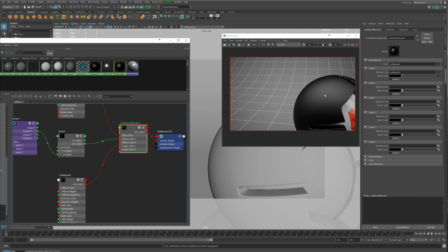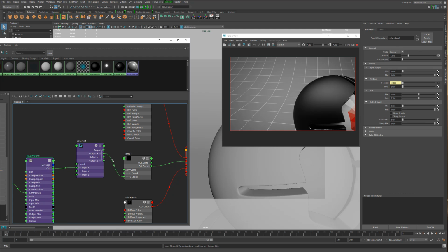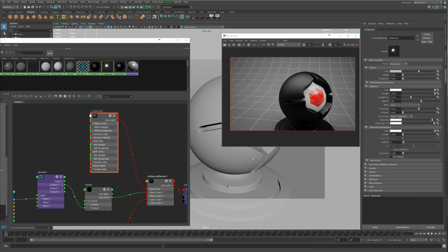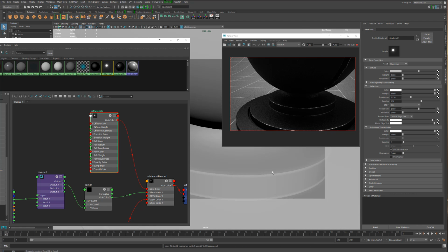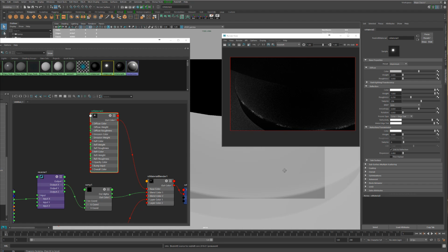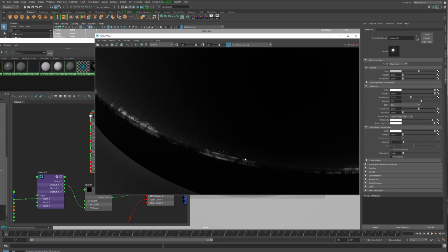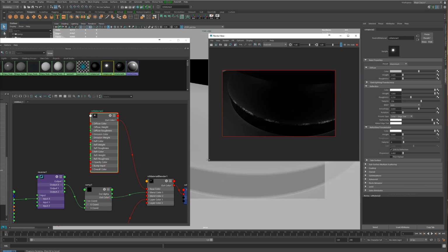So with this material blender, we could layer more things on top of it. And I'll actually layer some dirt on it right now using the same technique, except instead of convex, now we'll be using concave. And so on the material here, we could add some bump maps and get creative and add a lot of other neat stuff to this. But for now we've got our procedural scratches. If you zoom in, let's blow this up so you can see we got procedural noise going on these edges for wear and tear.